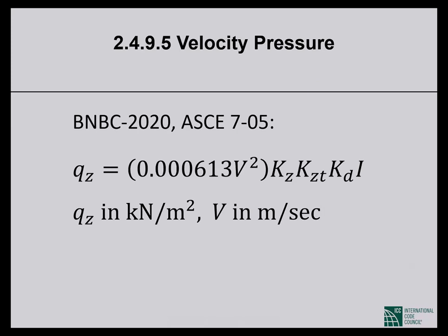Okay, so coming back to p equals q G C sub p. Remember the velocity pressure, the gust effect factor, and the external pressure coefficient. I will take you through each of those terms in detail. So we absolutely need to know those terms, and we need to know them intimately.